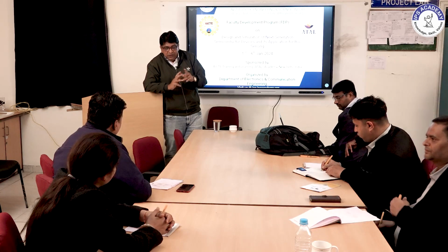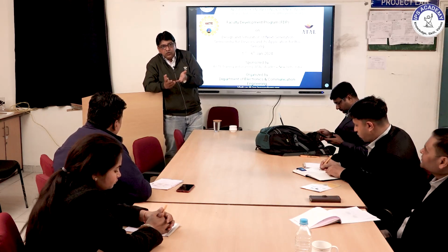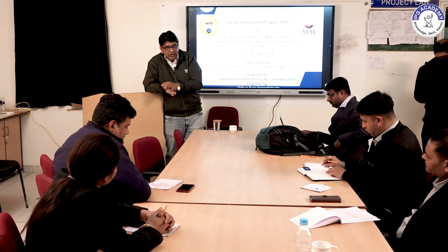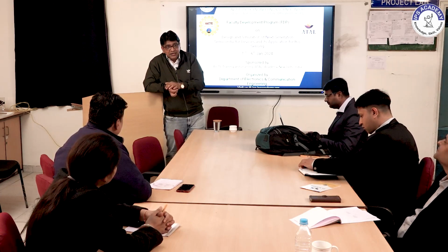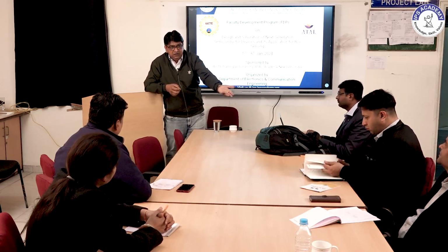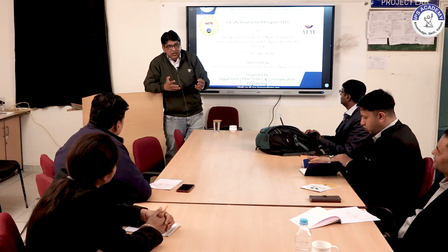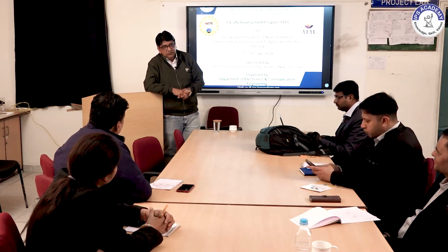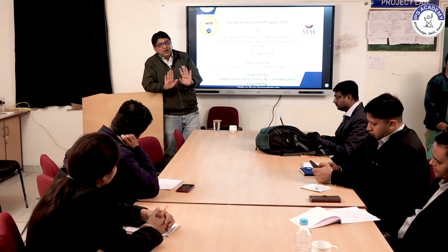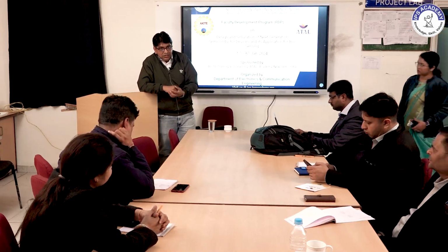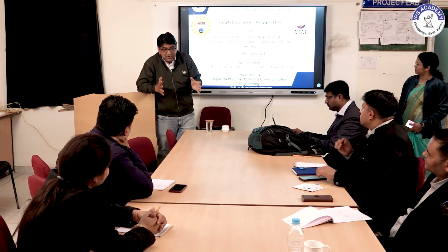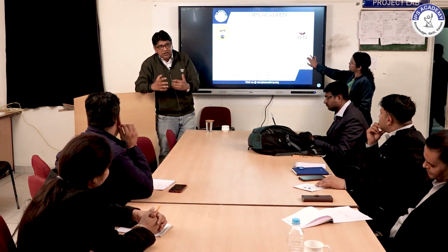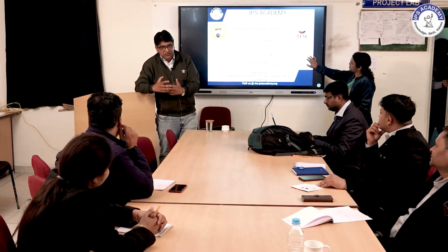And if you work on the short channel with respect to the long channel, we have to develop the mathematical model, because ultimately the goal is to develop a model that is useful for circuit design. But if you use the long channel device model for circuit design at the 14 nanometer node, it is not correct, because a number of non-linearities have to be included in our model so that it becomes more accurate. Getting my point, sir? So that's why I introduced the long channel. Those who work on device modeling, developing the mathematical compact model, first understand how the current is flowing and how to convert it into a mathematical equation. Then after that, we can introduce different types of non-linearity and make our model more accurate. That's why I mentioned this.